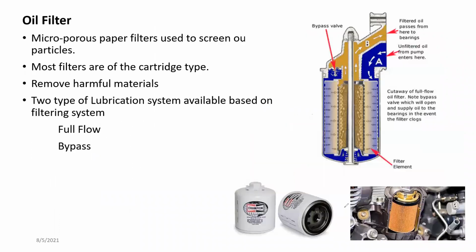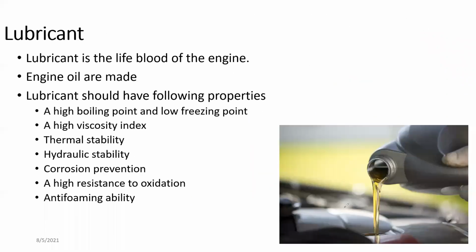And when the vehicle is moving, the lubricant is going to move left and right, so that could end up creating foam inside the lubricant itself. To avoid that, foam should not be generated. Foam means, you know what foam is, right? Like bubbles. Bubbles mean it can't maintain the pressure, and it could not be pumped as well. So those are the properties a lubricant should have.